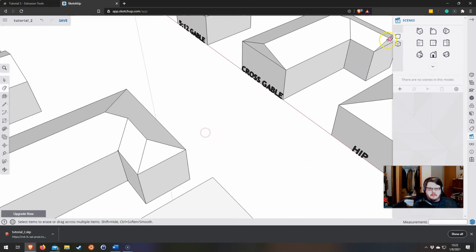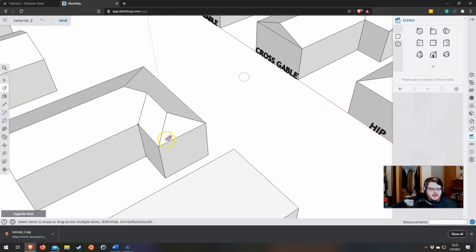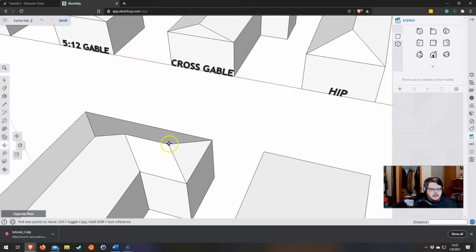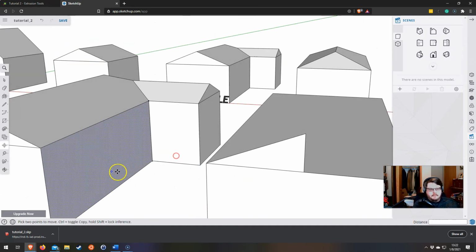But you'll notice that this one is flat and this one is not. So we can actually fix that by just grabbing the move tool, clicking on that corner, the end point, and then just pulling it this way. To make sure it locks to the red axis, hit the right arrow key on your keyboard, and then infer to this surface down here. So start dragging to the right and left, and then move your mouse so that it's on top of this surface, and you notice it pops back so that it's constrained to that plane, and then you'll have your thing.